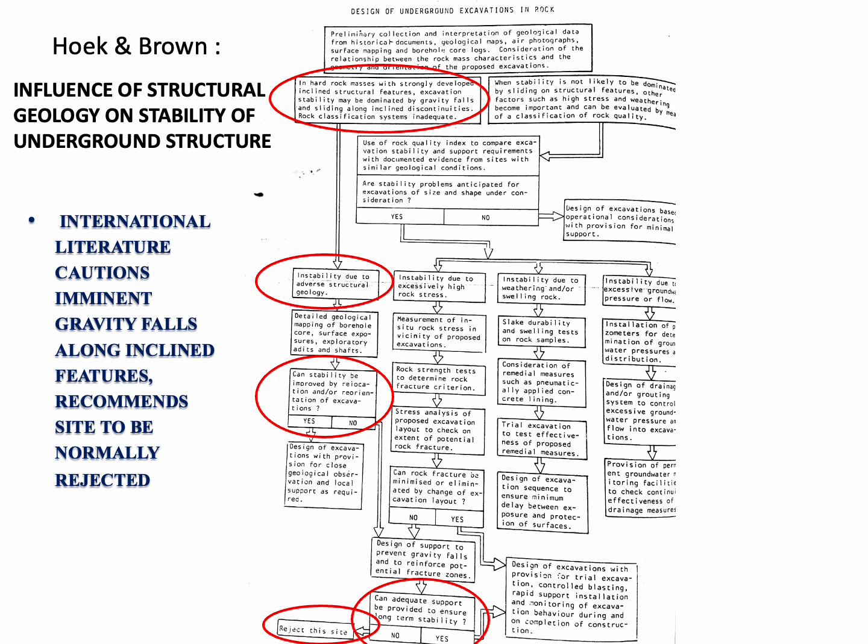It says, in hard rock masses with strongly developed inclined structural features, excavation stability may be dominated by gravity falls and sliding along inclined discontinuities.